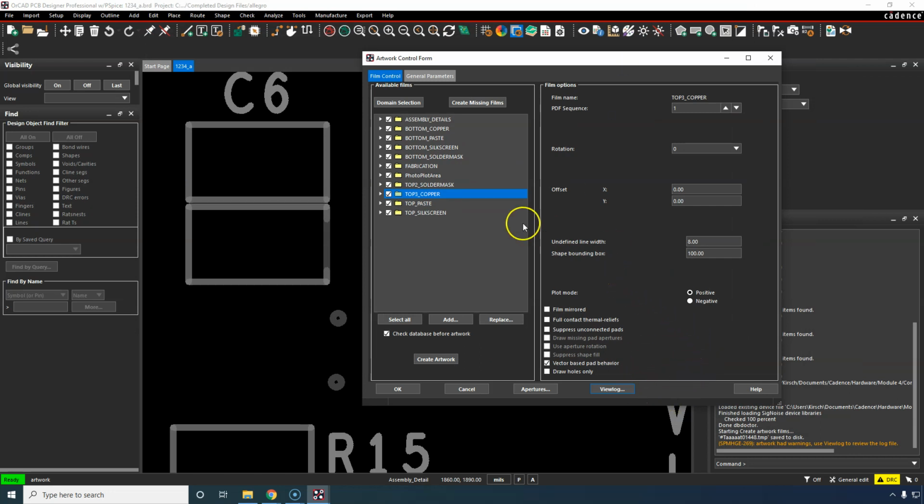What else do we have here? Something very important. Oh my goodness. Where I talked about solder masks so much. Actually, this is pretty okay. It's for your plot mode. The plot mode refers to what you see. If you want, you can make your plot mode negative. That comes out looking very interesting, but the manufacturer will still be able to interpret it once you let them know which layers are positive and negative. Okay, but leave everything positive.